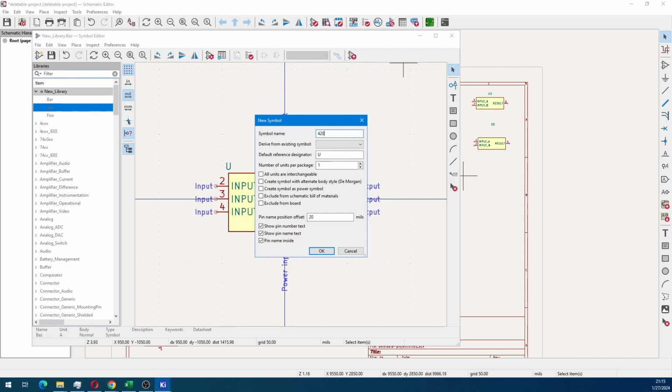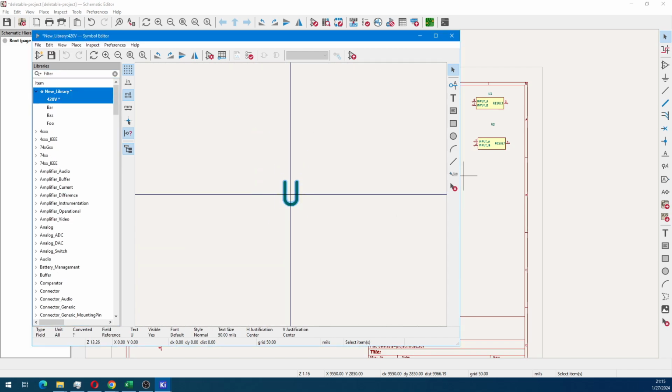First of all, they don't appear on the bill of materials, they don't appear on the circuit board. They can only have one pin. The value can't be changed once you've created the part. I mean, you can go back into your library and change it that way, but you can't change it in the schematic. And when you wire something to a power port, the power port acts like a global label, and I'm not sure if I mentioned globals too often in this series so far, but that essentially means that if you have a multi-page sheet, your power port is going to be the same net on each page.